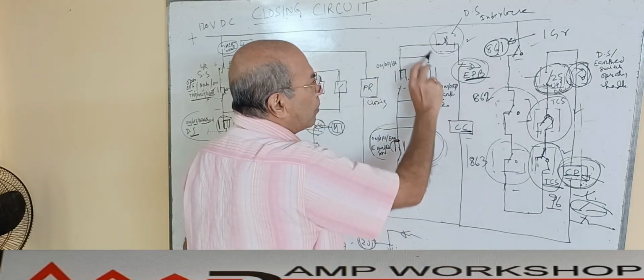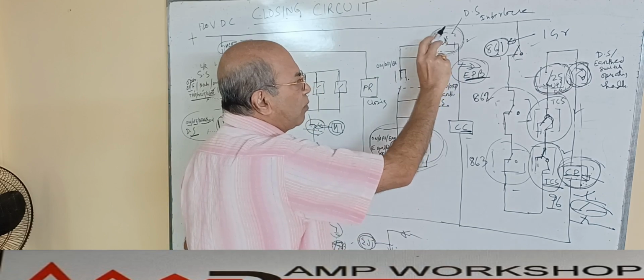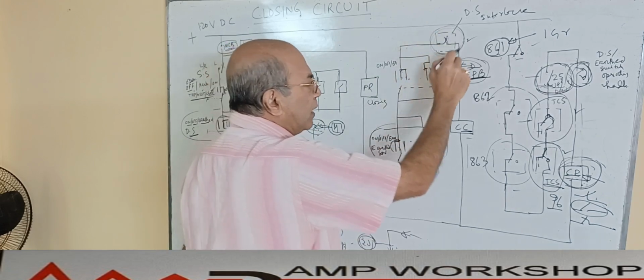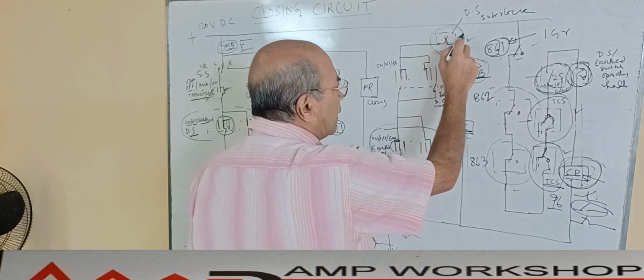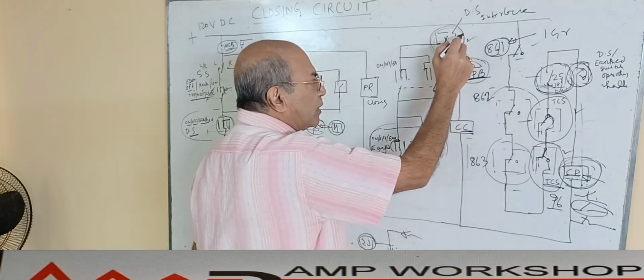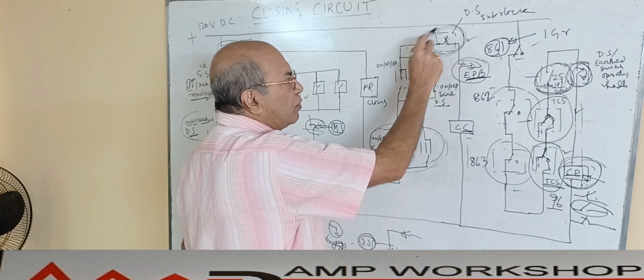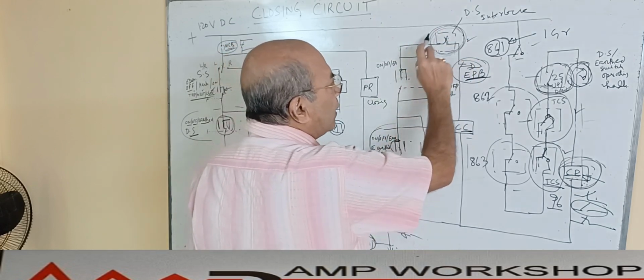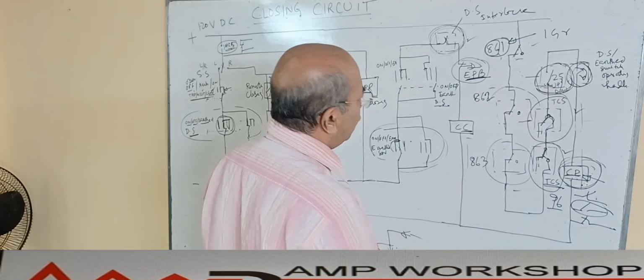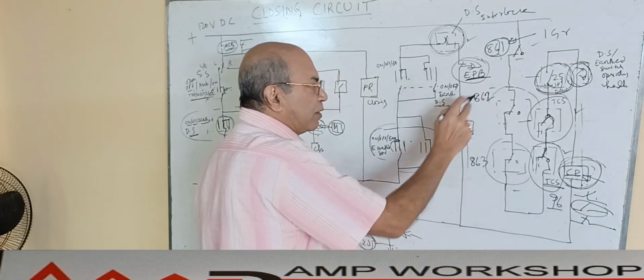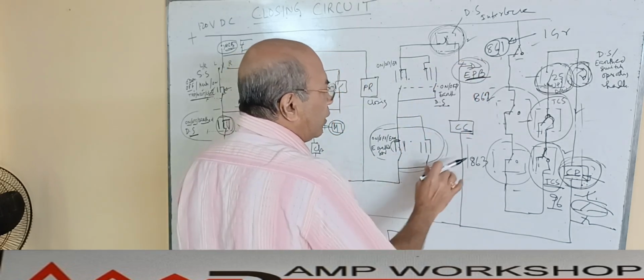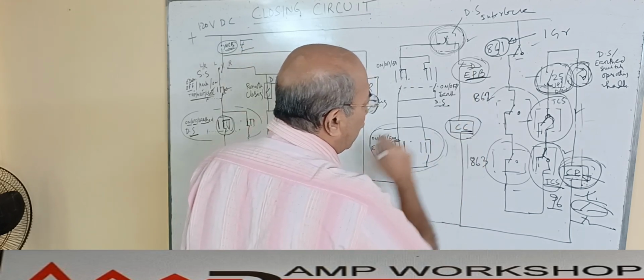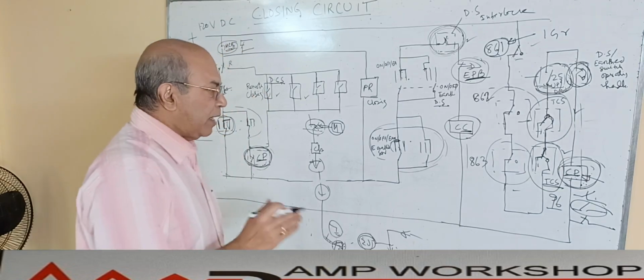Then the spring mechanism, trip coil spring mechanism or any other fault condition is not present in the disconnector switch or in the tripping circuits. That is also ensured from here, the disconnector switch. That is also ensured over here. The emergency push button has not operated.